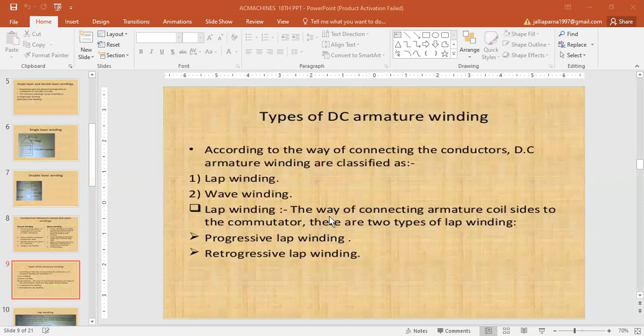A distance of approximately one pitch away, the transfer of the coil from one slot to another is usually made in a radial plane by means of a bend or twist at the back end.